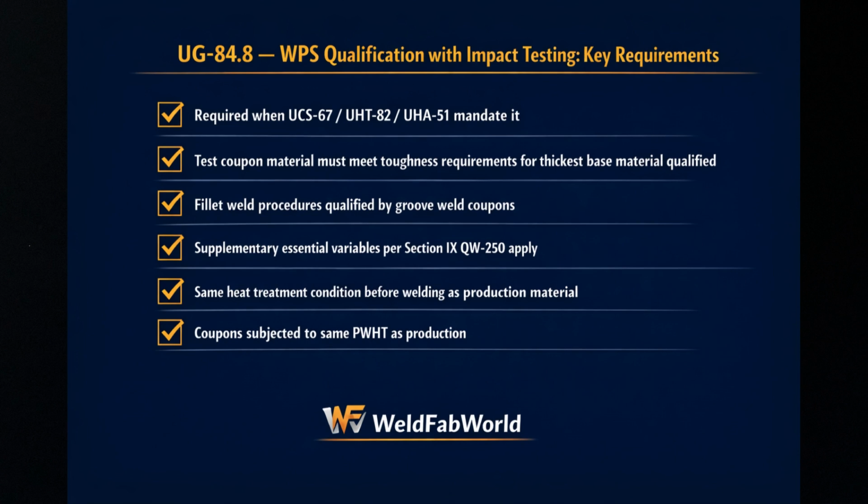And when impact testing is required for WPS qualification, the supplementary essential variables of ASME Section IX, paragraph QW-250, automatically become essential variables. Any change to those variables means a new PQR. This is a huge point for welding engineers. A change in heat input, preheat, or interpass temperature can invalidate your qualified procedure when impact testing governs.